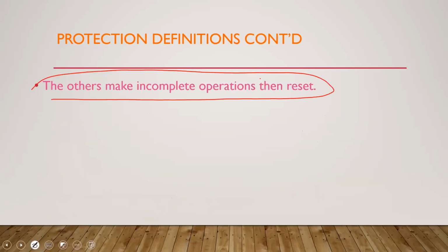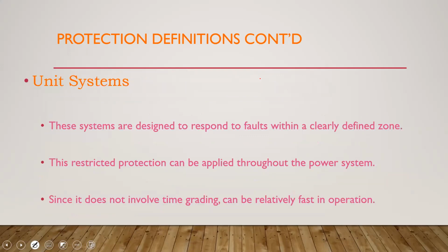Okay, so the other option now. We talked about time graded; now we have unit systems, and I'm beyond the 40 minutes that I had promised Mr. Clark, but we're getting there. These unit systems are designed to respond to faults within a clearly defined zone, and you can't use them right through the power system. It is heavily used. When we talk about differential systems, those are unit systems.